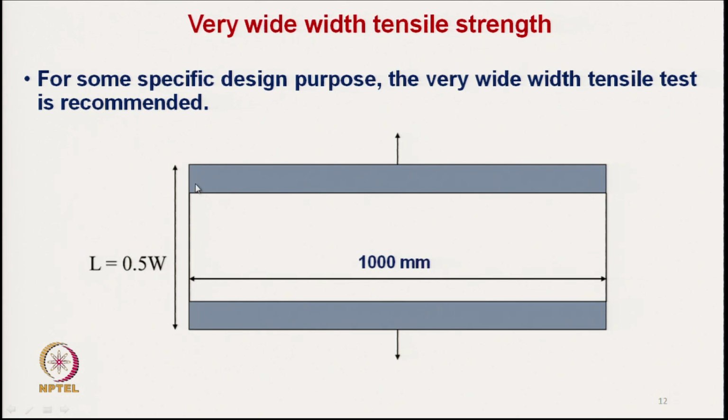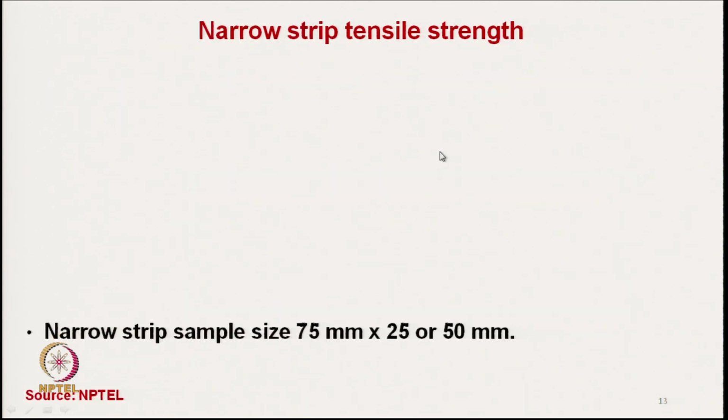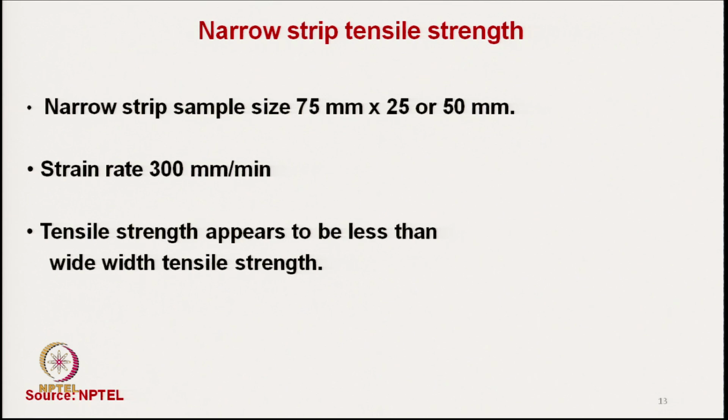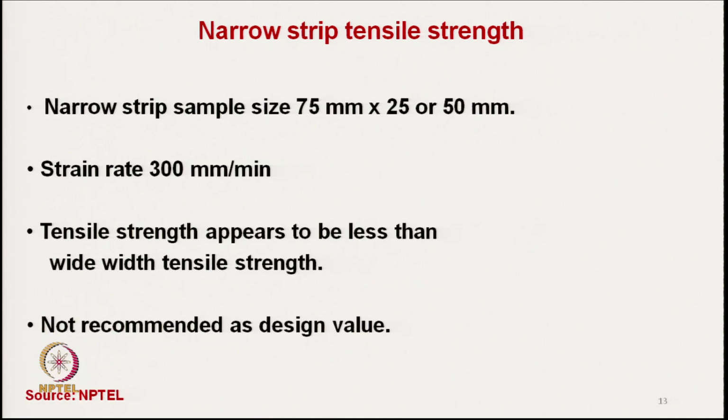So, this is sometimes recommended for geotextile application. Narrow strip we can test for just getting the idea, the index value we can get. The tensile strength appears to be less than the wide width tensile strength. As I have already mentioned, this test is not recommended for geotextile design, only for getting the idea about the